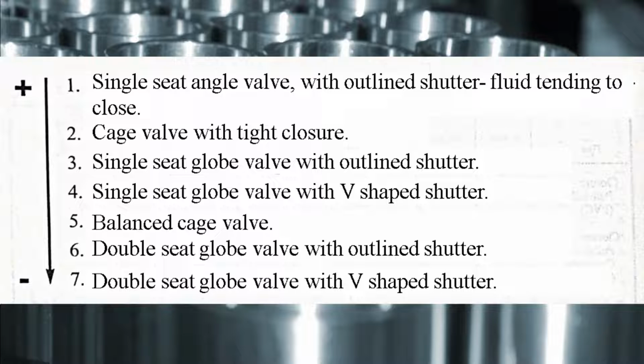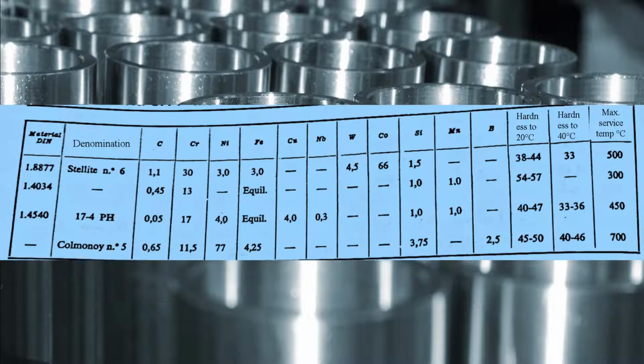The angle valve is more favorable than the globe valve, since its body and obturator are not subject to such a high degree of variation in the path of the fluid fillets. The plug and the seat are the most affected by erosion.